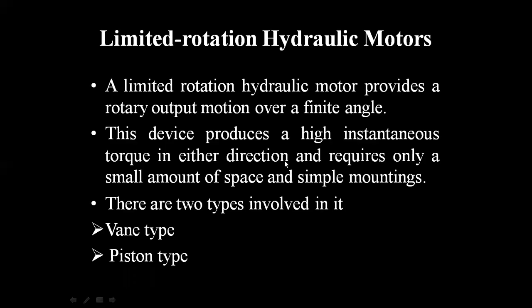Next topic is the limited rotation hydraulic motor. Another important topic. As the name itself implies, there is only limited rotation involved in this casing. Inside the casing we will have the vanes. The vanes rotate in a limited way only, in a limited space, at some finite angles.